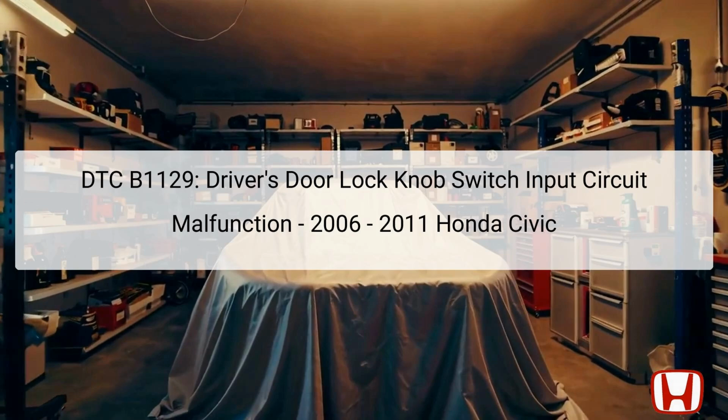The DTC B1129 refers to a malfunction in the driver's door lock knob switch input circuit. This error means that there is a simultaneous input of lock and unlock signals, which can create confusion in the door locking mechanism. The driver's door lock knob switch is vital for controlling the locking and unlocking of the vehicle's doors. It's located on the driver's door panel, easily accessible to the driver for operation.